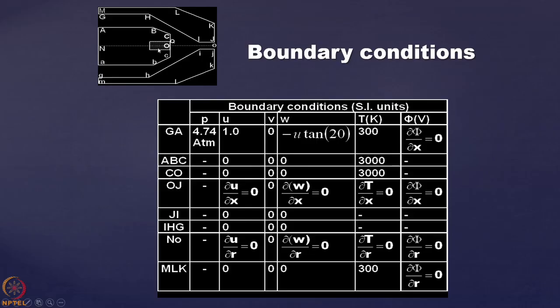So you have to do some experiments at that particular temperature. What is the current density distribution? Or when you are passing a current, you know that you have to do the current conservation equation. So if you integrate current over this area, that will give you the total current. So whatever profile you are choosing, the parameters should satisfy the total current. So that way you can define a current density over this cathode zone. Okay. So that again will be a boundary condition when you are going to solve this kind of system.